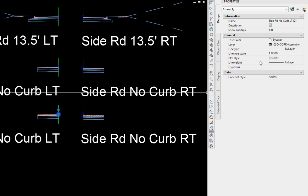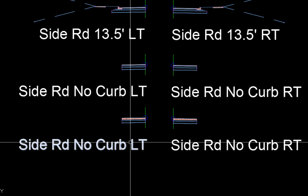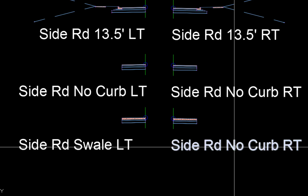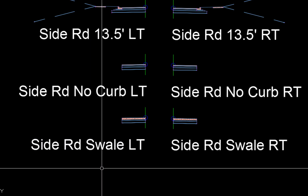Pick the assembly marker. Properties palette. Side road swale left. Enter. Escape. Pick the other assembly marker. Side road swale right. Enter. Change the text. Escape. Side road swale. Repeat for the other side. Side road swale. M to move the...